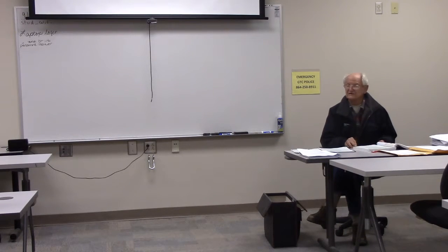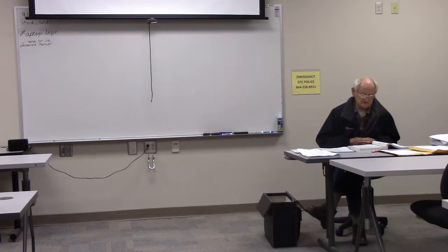Did we do the section review? Y'all got your books? A receptacle is usually housed in a pull box, round box, junction box, or device box. Device box. If a box can hold 8 number 12 wires and contains a cable clamp, a switch, and a loop conductor that is 13 inches long, the maximum number of additional wires is 3.